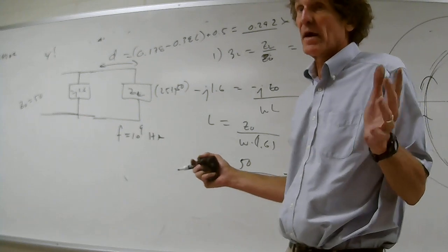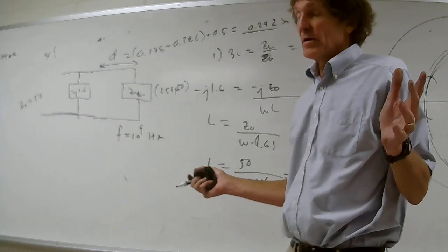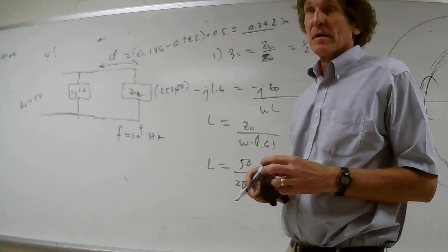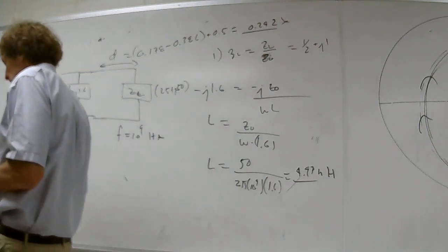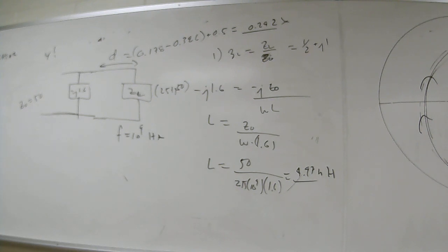Bad design. An inductor in parallel shorts out DC. If you have a choice, don't do it. You don't want that. I got other stories about it, but you really don't want that. I'll tell you why. If there is any DC on that line, that inductor will probably burn out because it'll act like a short and it acts like a fuse. Inductors will pop in a second unless they're really thick wire.